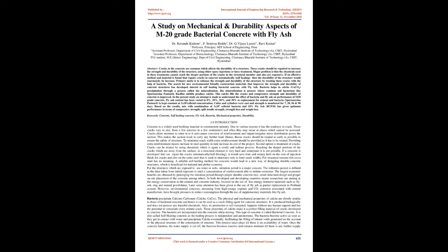Bacteria help in calcite, CaCO3, precipitation through a process called biomineralization. Biomineralization is a process where common soil bacteria like Sporosarcina pasteurii and Bacillus subtilis produce calcite. This calcite fills the cracks, and the compressive strength and durability of concrete is improved.